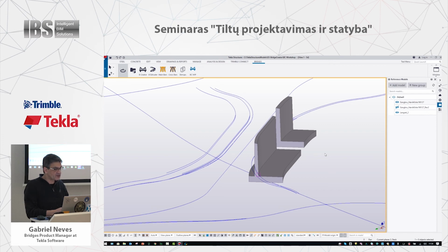I did. My first job was 8 underpasses, 6 weeks, 2 guys, and we delivered. And then after a couple of months, a Tekla guy came to the office in Scotland, and I was showing off our first job, it was great. They said, oh, that's great, I bet you used cloning drawings. Cloning drawings, what is that? Oh, don't tell me every wing wall, every drawing of the portico you created from scratch.